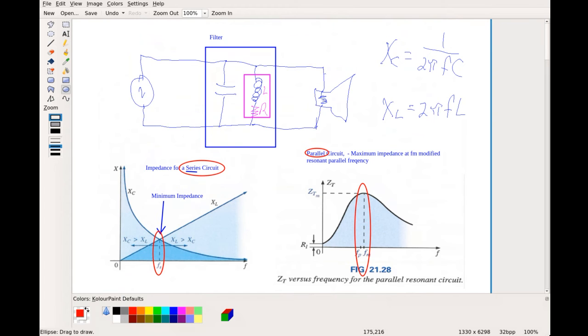Okay, and so what we're doing is, if our frequency is within the resonant frequency, or at least within that bandwidth, then we're going to pass that band of frequencies. Okay, so what we talked about today are band pass filters. We're passing the frequencies within this range, okay, within whatever our bandwidth range was.